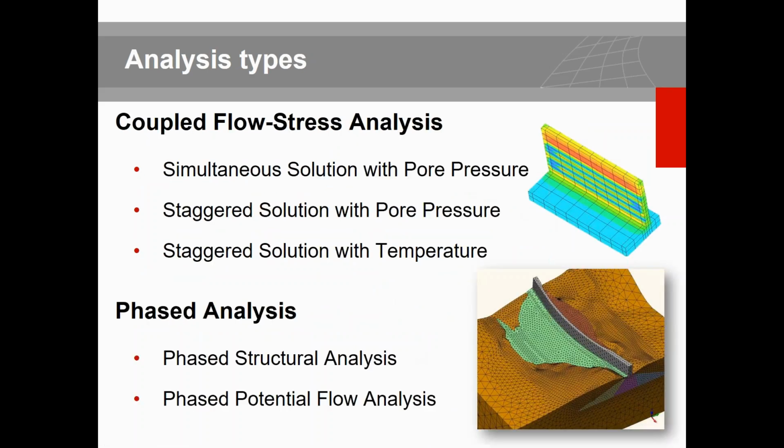With respect to the flow analysis, you need to couple that with the stress analysis, because when there is heat, when there is a groundwater flow analysis, you want to see how the effect of the temperature gradient or cooling, or how the increase of the pore pressure or the decreasing of that is causing a deformation in the model. So Diana provides the platform that you could define this interaction as a fully coupled or semi-coupled analysis.